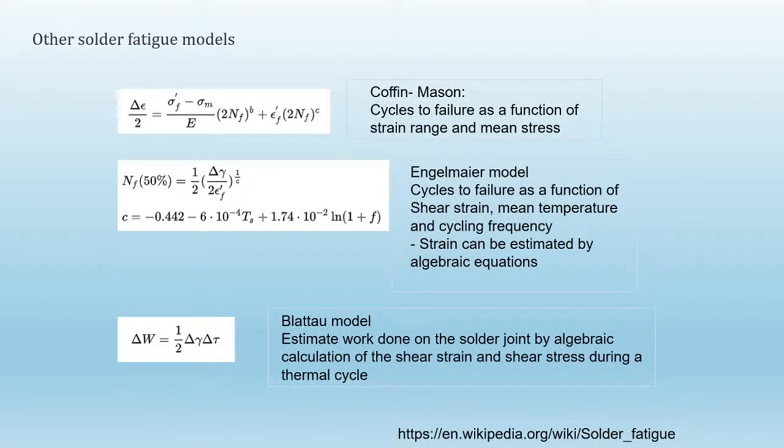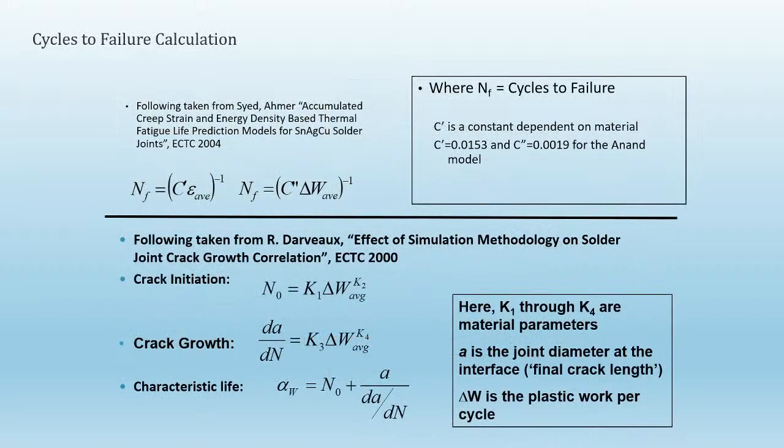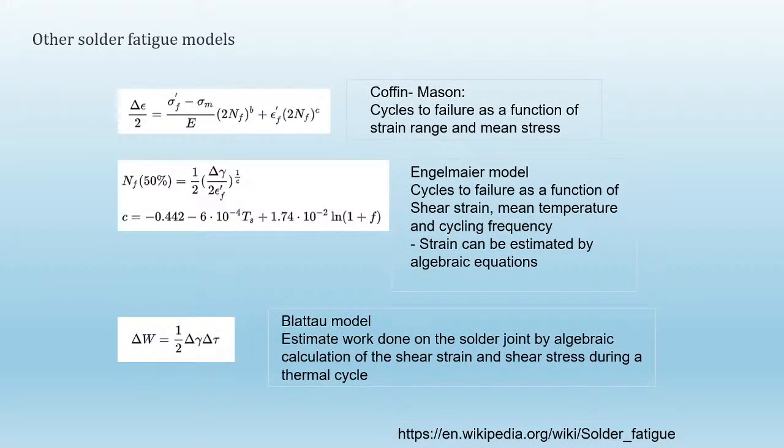So there are other solder models available. These are kind of the published work, and this is considered, based on my experience, what most of the people are doing. So if you look at the main packaging houses, the people that develop high power microprocessors and chips, almost everyone uses this method for solder joint analysis for high temperature cycle. But not everyone does very high power systems, right?